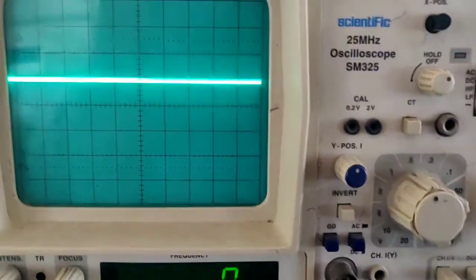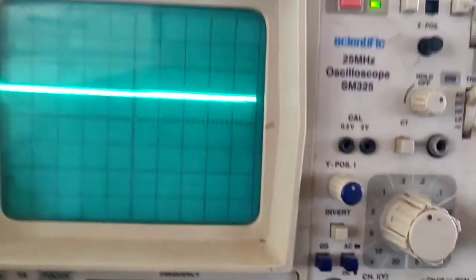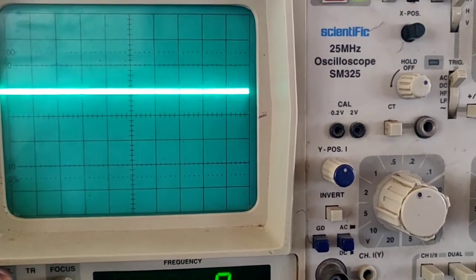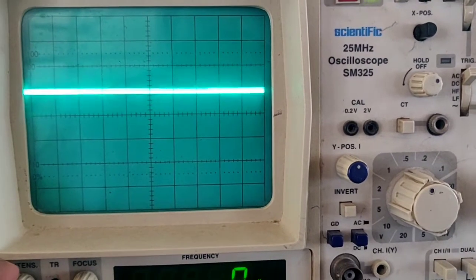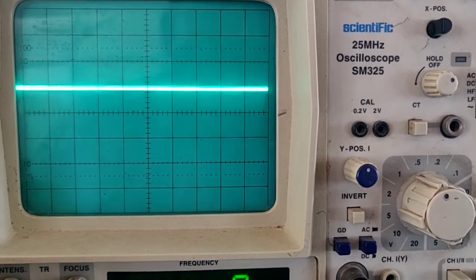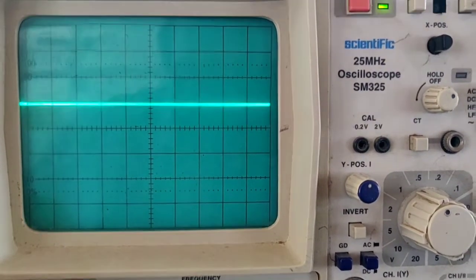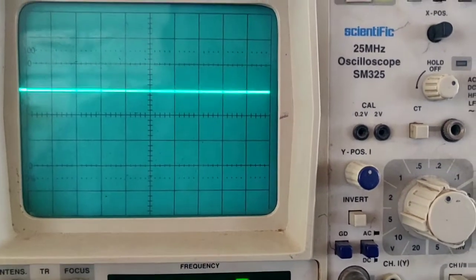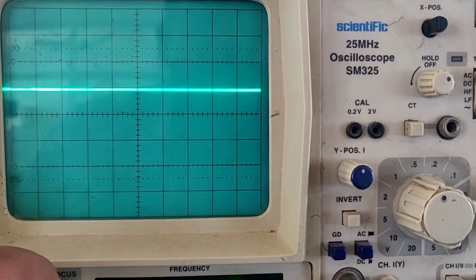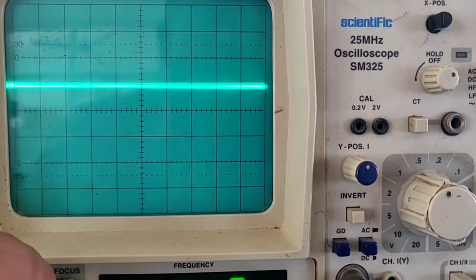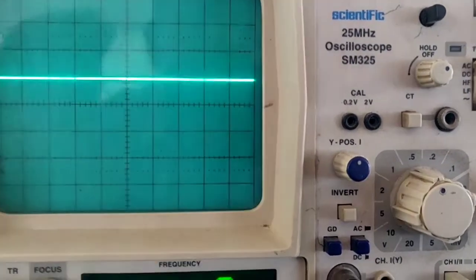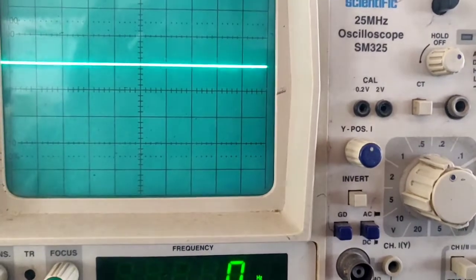Now if the intensity is maximum, adjust the intensity to a suitable level. See that this is minimum and this is maximum. If you keep the brightness at maximum, the phosphor screen on the CRT will get damaged. So adjust it according to your taste. The next control is focusing. See, this is out of focus now, and these are also out of focus when I keep it at minimum. So position it exactly like this. So you understand how to do the initial things.